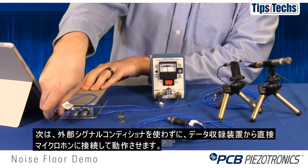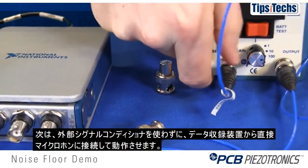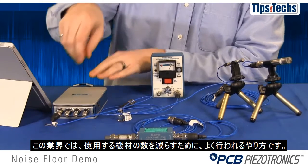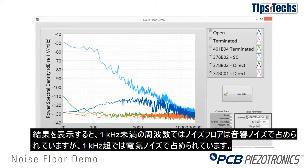So the next thing we can do is bypass the external signal conditioner and power the microphone directly from the data acquisition system. This is often done in industry to cut down on the number of pieces that you use. When we do this, we see that the noise floor below 1 kilohertz is dominated by the acoustic noise, but above 1 kilohertz, the noise floor is dominated by the electronic noise.